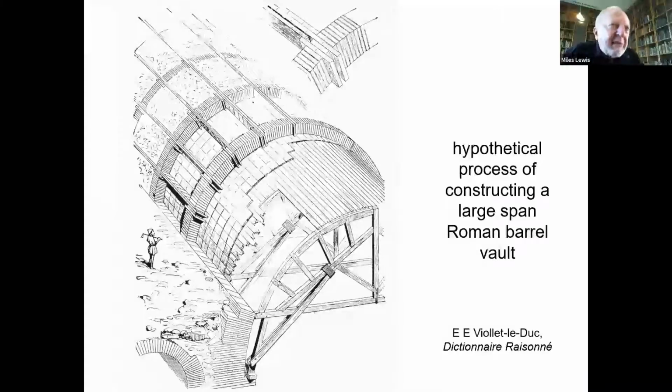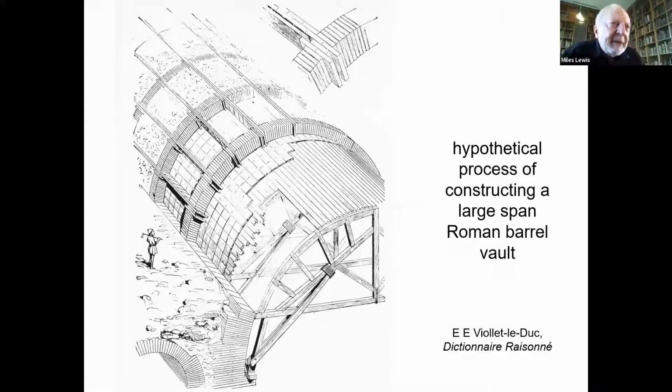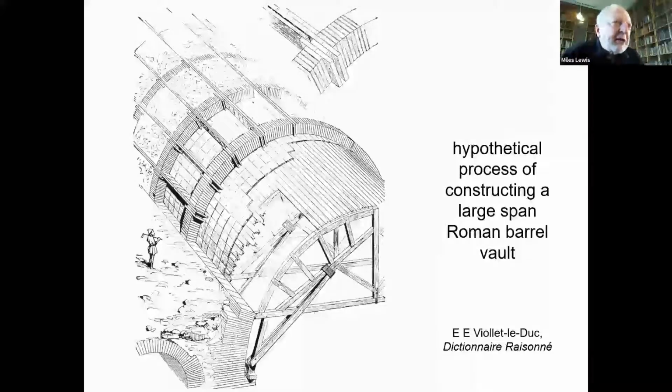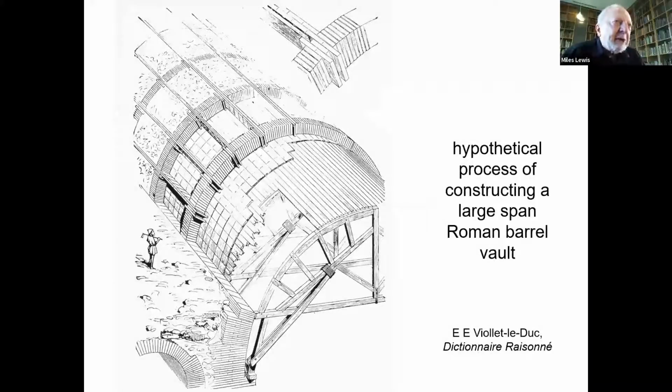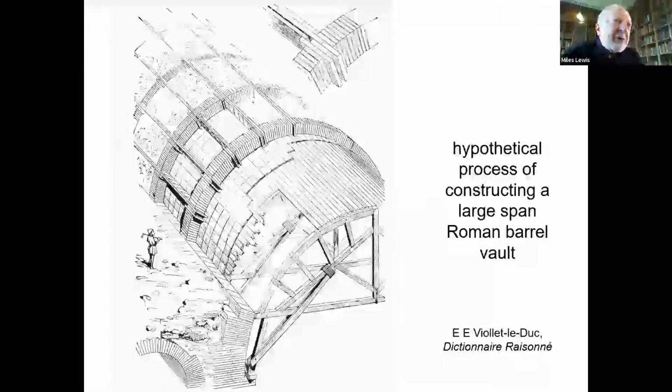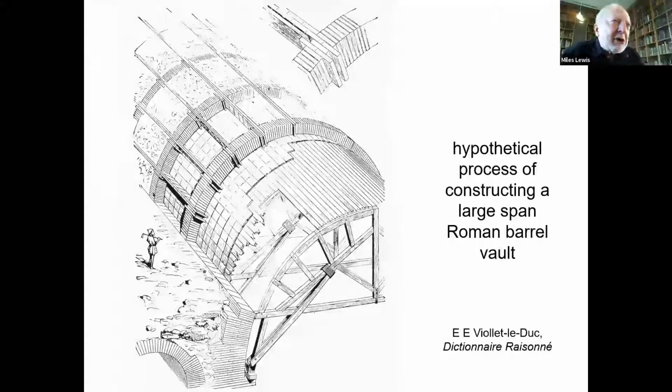But in this case, they've made the formwork, which is timber, and they put tiles onto the timber. And the tiles are going to stay in the concrete. So when you pour the concrete, you pack it into those compartments. The brick ribs provide a sort of armature, and then you just pack the concrete between. You end up with the sort of homogeneous concrete and brick substance with the tiles on the face below, so you don't see the concrete from underneath at all.